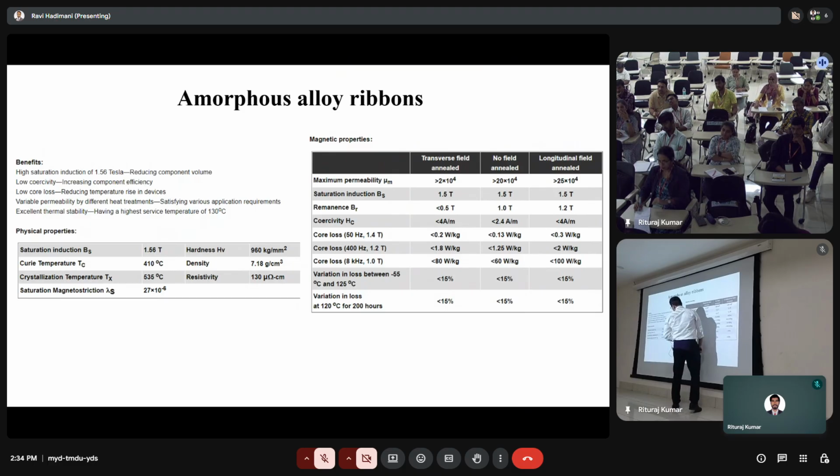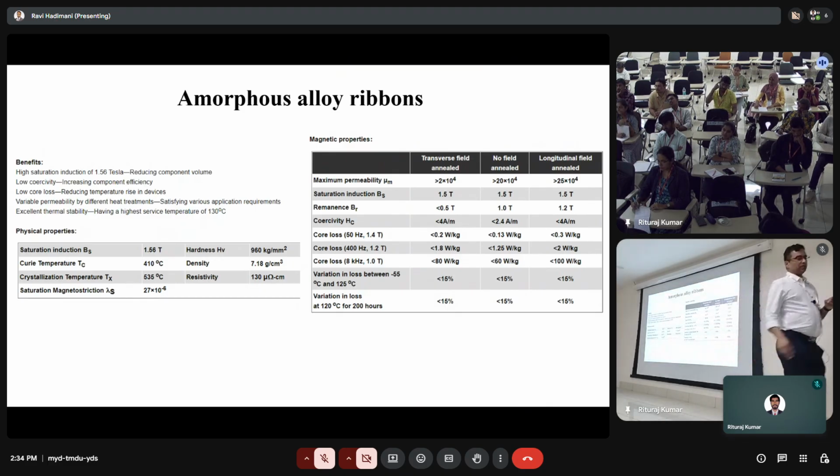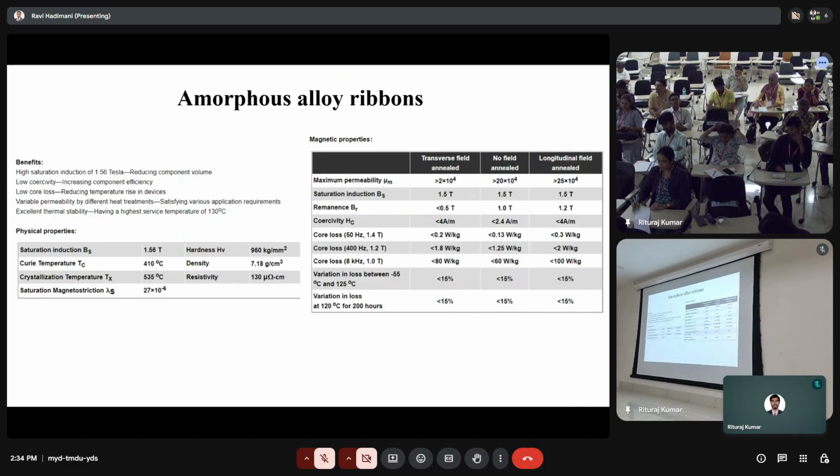For electrical steels, you want to have lower resistivity. Actually, not too low, because if you have too low, then you will have eddy currents. Okay, and again, I don't want to go over all these parameters. What basically this slide is showing is that many properties of metallic glass or nanocrystalline material are far superior to the regular polycrystalline material.